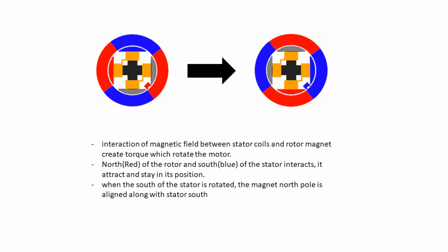In this motor, the rotor spins 180 degrees when an electric current is run to the armature. To go any further, the poles of the electromagnet must flip. As the rotor spins, the brush makes contact with the stator, flipping the magnetic field and allowing the rotor to spin a full 360 degrees.